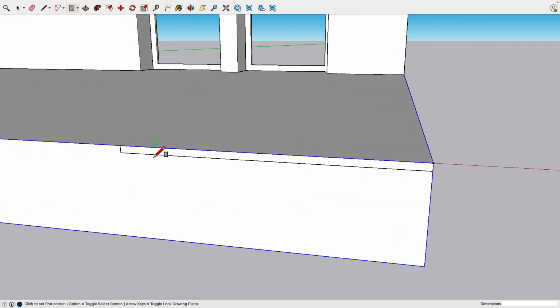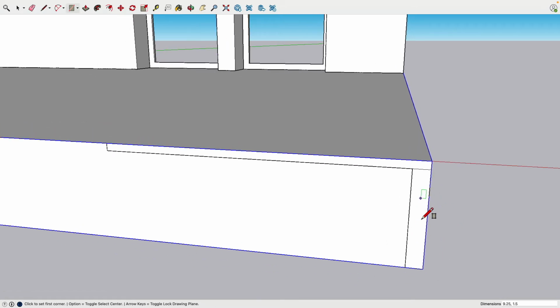That is actually a wooden board which sits on kind of like joists which are 9.25 plus minus 1.5 there. So this is a joist. These are vertical, this joist, and then this sits on top. And then that's kind of like called the subfloor.